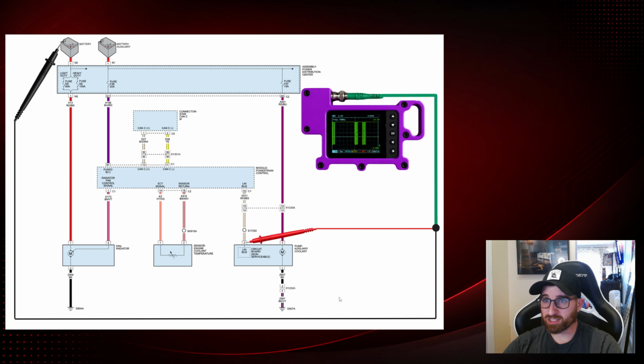Also, while I was here, I pulled out my little U-scope, wanted to do a little test just to make sure I had good communication. Now this is also with this connector unplugged, just as a note. I moved us back to a negative lead at the battery and our positive lead right here into the connector pin number 2, again utilizing that terminal kit from AES Wave.